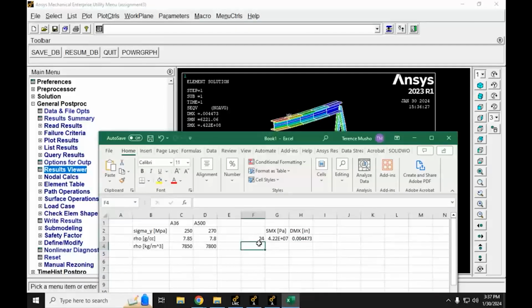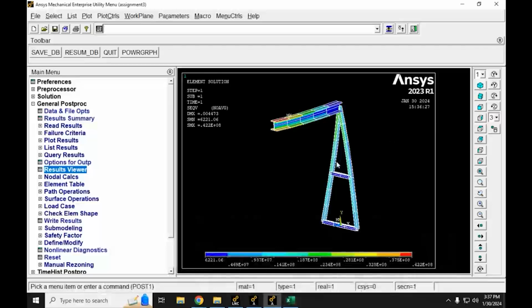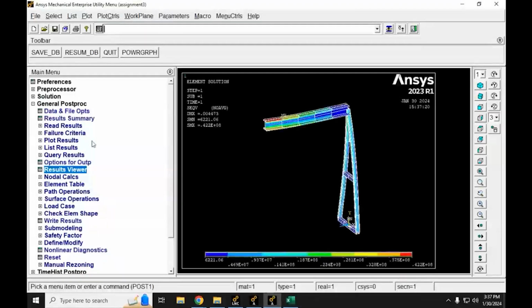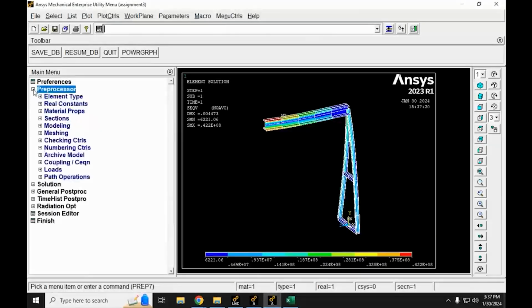So what I'm going to do is halve the edge length, right? Currently each element is roughly 2 feet long. I'm going to make them now a foot long. The way that I do that, and again, just watch up here, don't do this to your model.